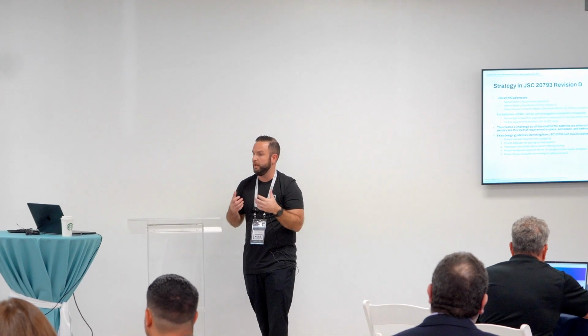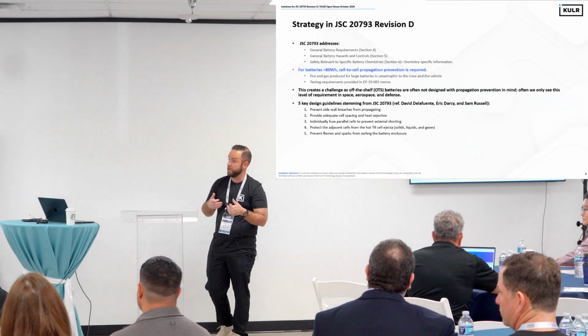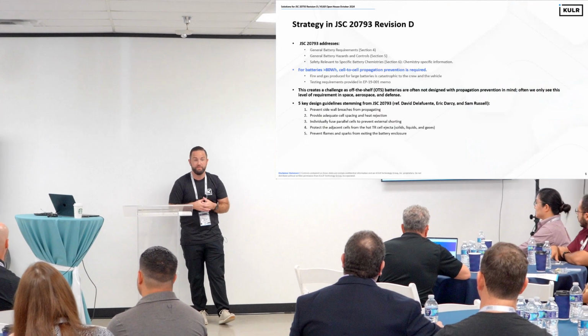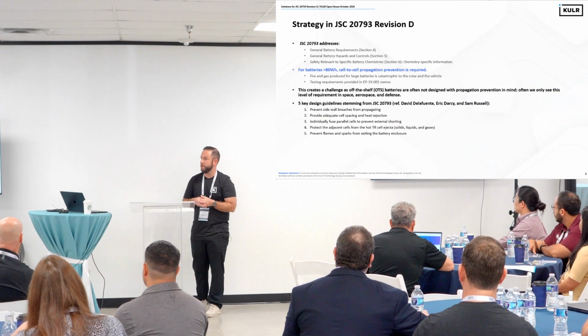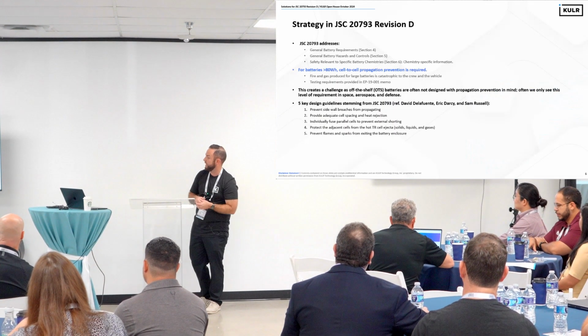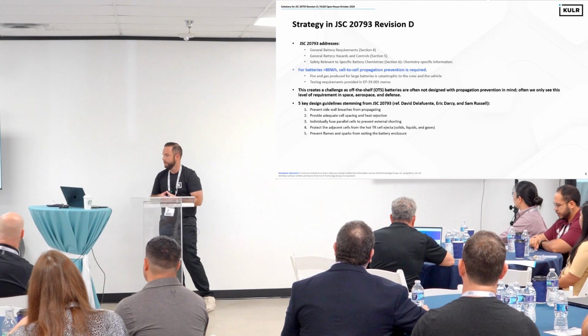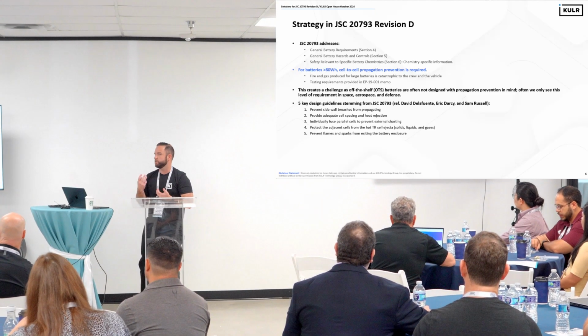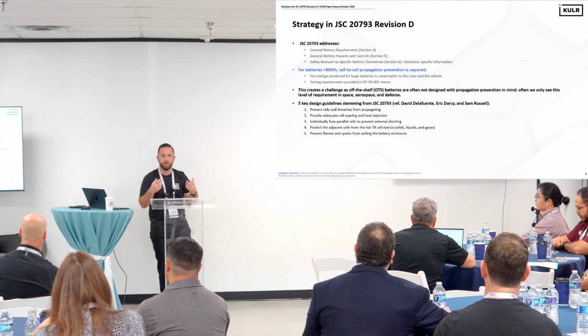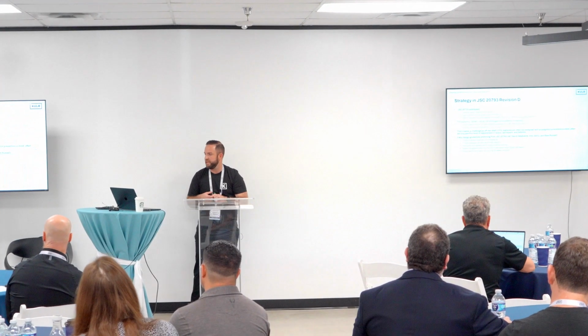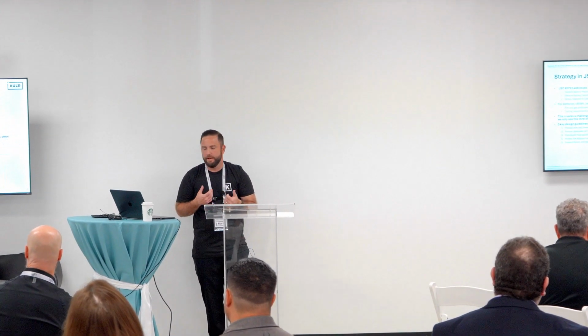I would encourage you, if you are in the process of battery design or you deal in battery safety, I think it's a great one to be familiar with. A lot of good information in there, and in particular, a lot of good design practices that we'll talk about later today. But ultimately, I think there are three key sections that you're going to find when you start digesting it. The first is general battery safety requirements. These are basic battery safety requirements for batteries of all kinds, right? The standard doesn't just address lithium-ion batteries, it's going to address primary batteries as well and other chemistries.